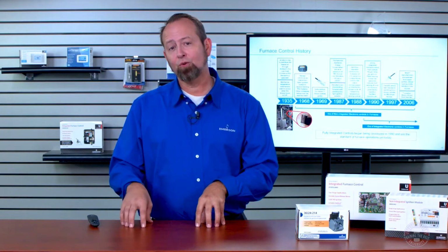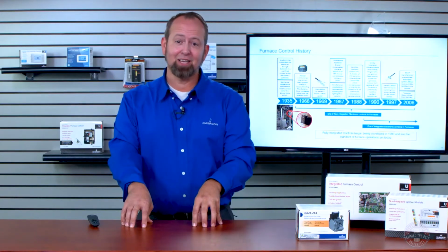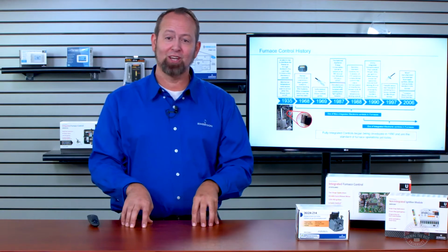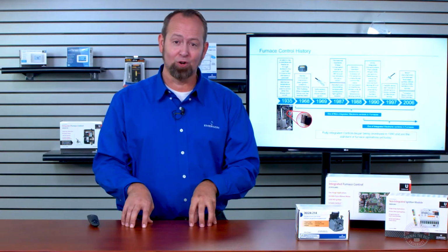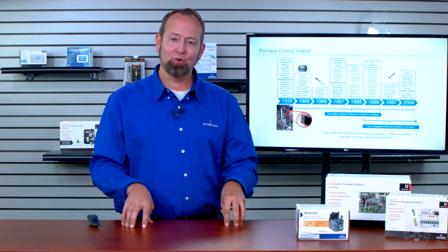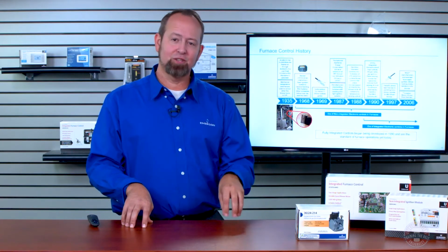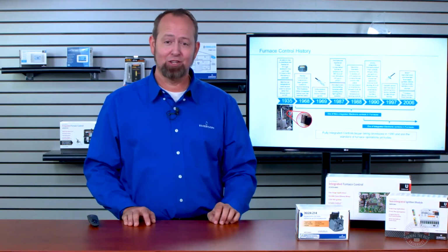And I researched to see if that was the correct control for that furnace. And come to find out, at some point in time, that control had been replaced. Some technician had updated that control to a 120-volt igniter or ignition system on the board, but left an 80-volt igniter and had continued to put 80-volt igniters back into it.